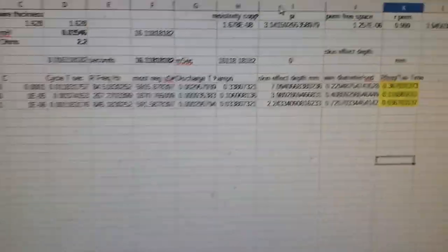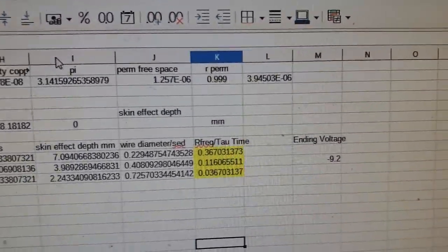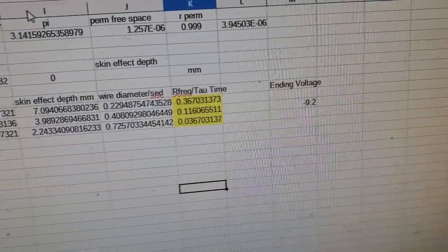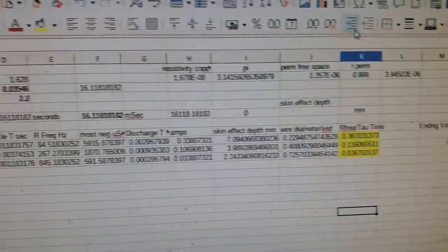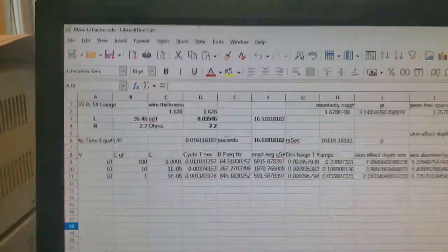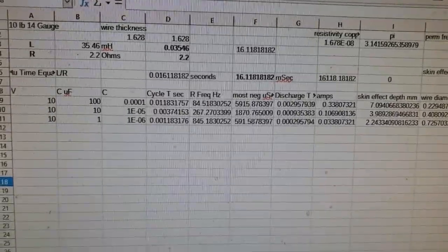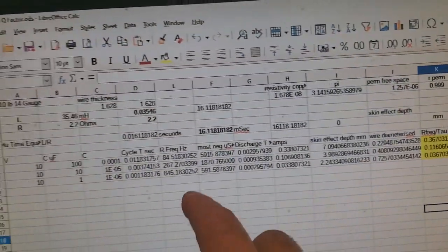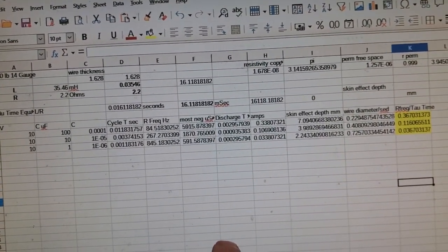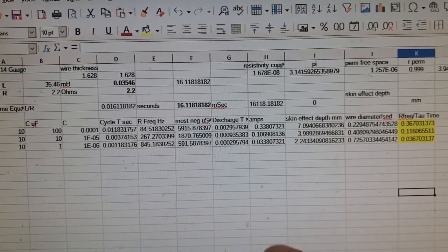But what I can say is that it gives you a nice starting point that you have over 90% of your charge. In this case, 92% of your charge is back right where you want it for the next pulse. I don't know how well it would work in practice, but that's something that would be interesting to do with a pulse motor. What are the other points that I want to cover here? Well, one thing in the back of one's mind is, you went from 10 to negative 9.2. So that's a fairly undamped LC tank circuit. That's going to ring for a while.